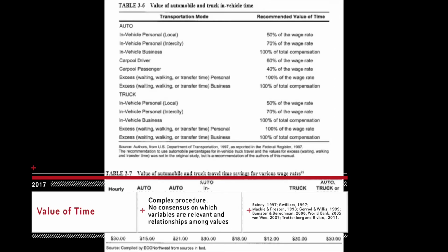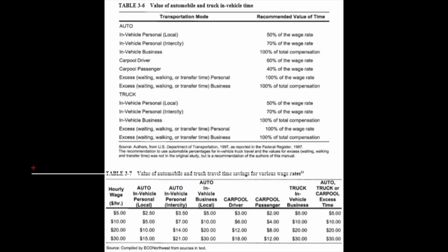Value of time. While travel time is easy to estimate on a new road or rail project, the changes to current traffic flow and mode of public transport are difficult to model and very complex. Adding to these complexities, indirect methods of valuing travel time have been used, which further adds to the inaccuracy of the benefit. As a general rule, freight and business trips are valued highly, and personal trips are valued at 25 to 70% of the user's current wage.